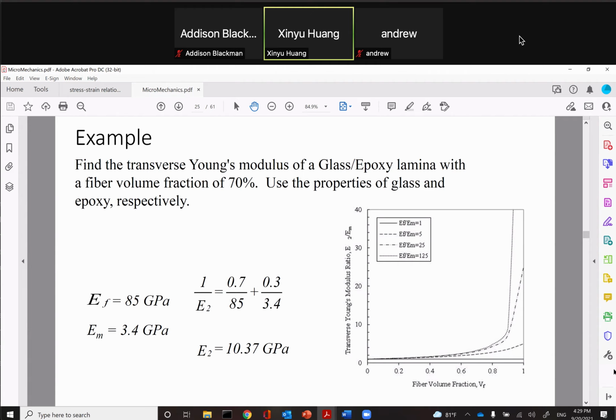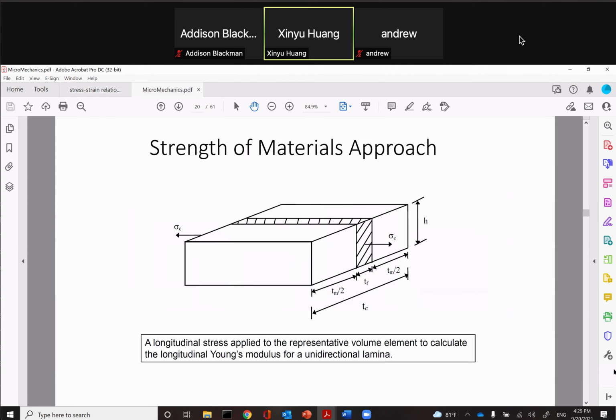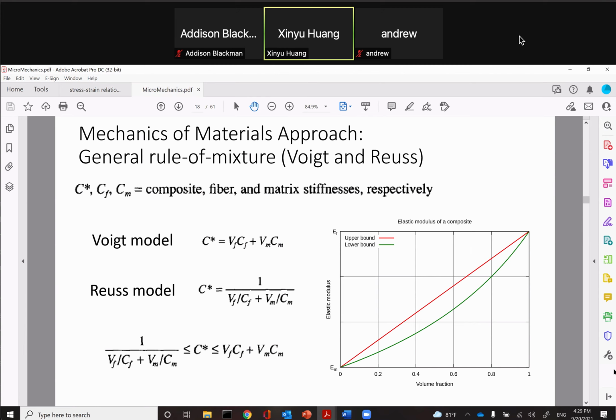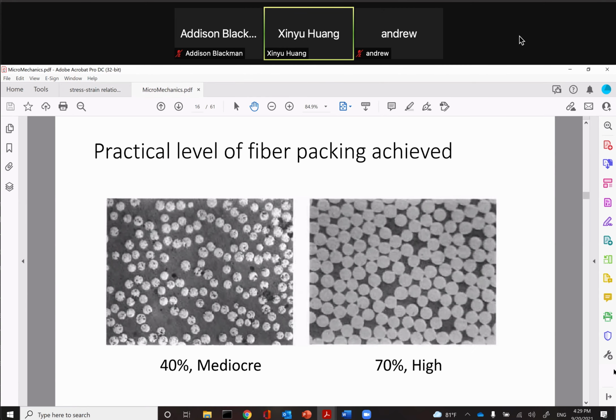So basically, if you put a fiber together in a composite like this, you remember the strongest direction of the fiber is along the axis of the fiber, right? So you have huge reinforcement effect if you load in this direction, but you also have a reinforcement effect in the other direction as well. So in this direction, they also make it a little stronger, but not nearly as much as the axial direction.